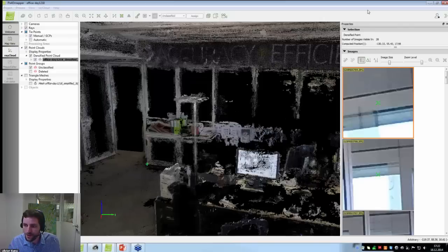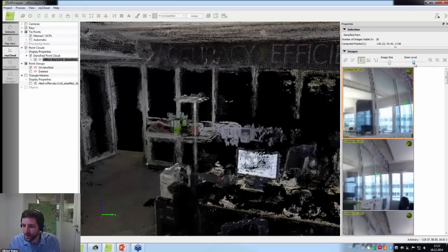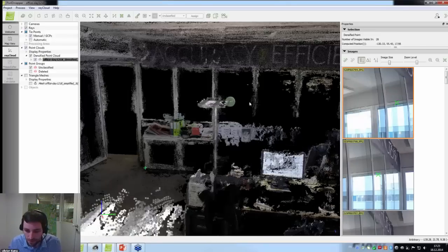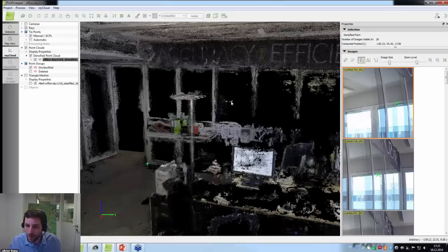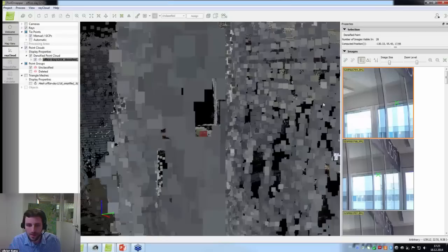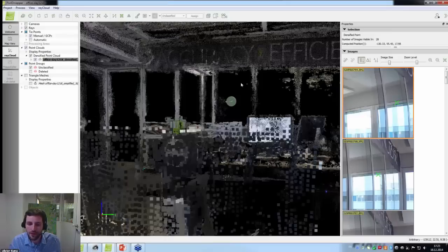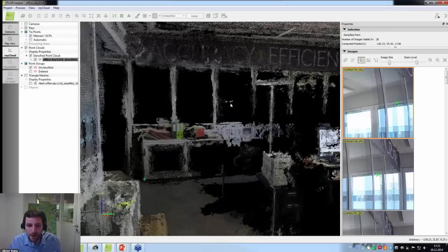So if you look in the ray cloud, what type of images is that? Well, this is a window, and it's a transparent, reflective window. And this type of material, as opposed, for example, to a laser scanner, cannot be well reconstructed in 3D in the point densification. So this area will have very little points, and the points they have are very likely to be very noisy, because the surface is not consistent. If you look at different angles, because of the shiny reflection, things will look different.